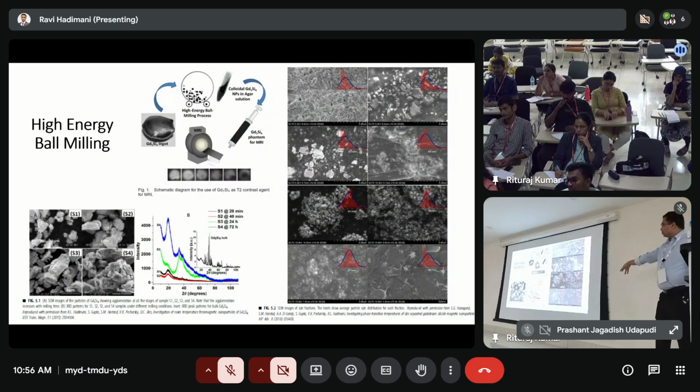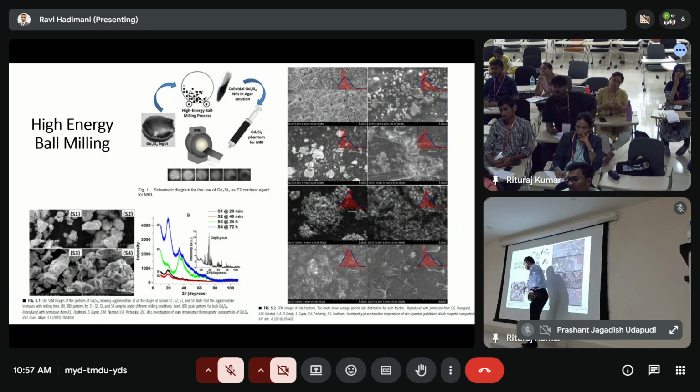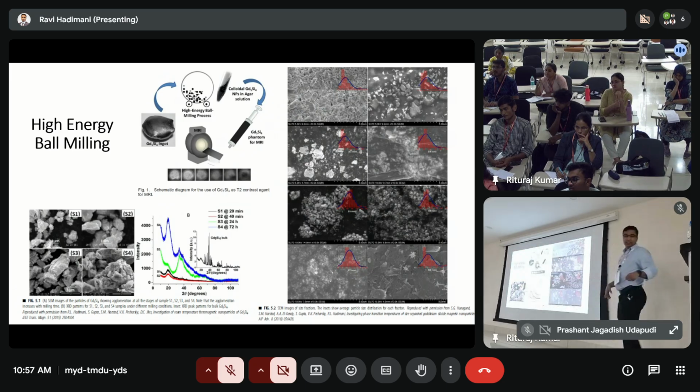And this is our ball milled nanoparticles, and you can again get different sizes. When we ball mill for more than an hour, it's completely amorphous, the black and red. So we have to use some media in between to absorb some energy back and retain the crystal structure.